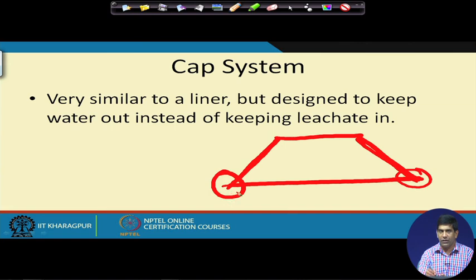Sometimes the civil construction job has to be done very carefully, otherwise you may have a scenario where this liner does not meet very well, and then you may have intrusion of water coming inside the landfill. But once you have this, you will go like that, and then again on top this cover is separate. So, you have to have some sort of connection here and here.